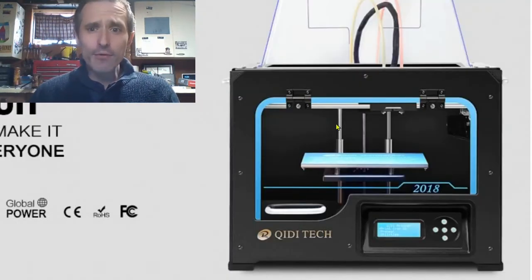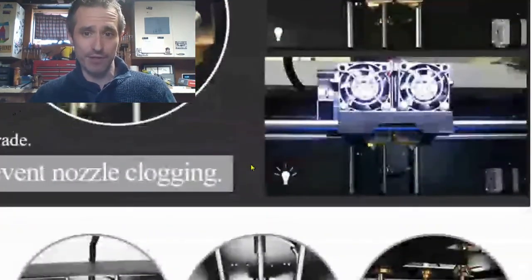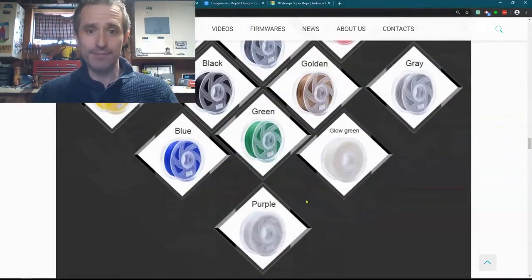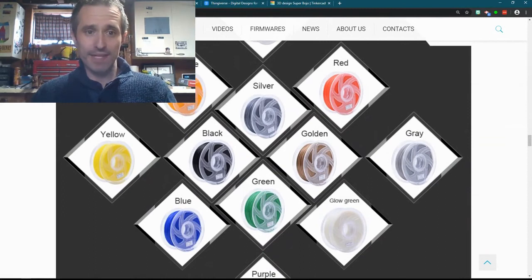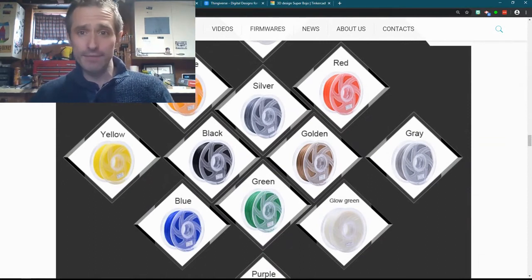So we've got this 3D printer. We've got rolls of plastic on the back of it. And those rolls of plastic are just like this. Okay. And they're filament. They're called filament. And I get them for, I think it was like $25 a roll for ABS. There are fumes to ABS, so you want it in a well-ventilated area.